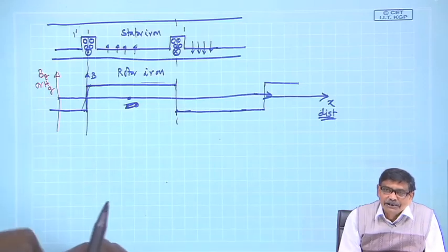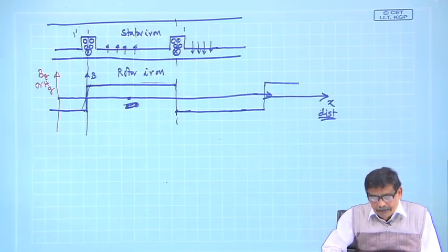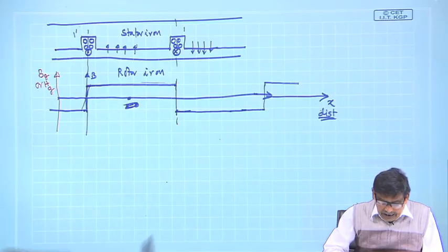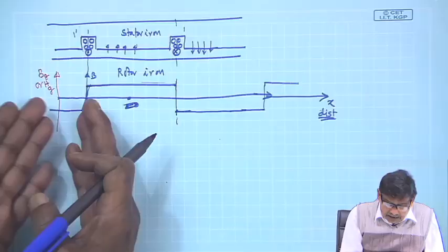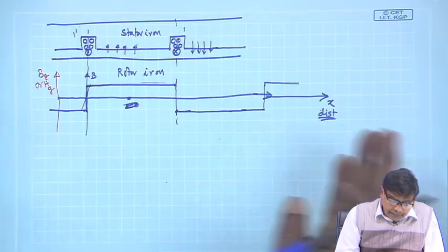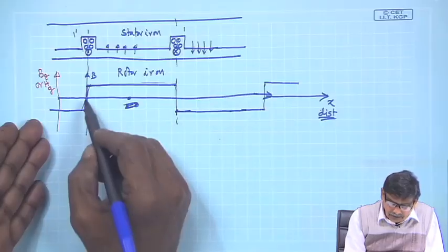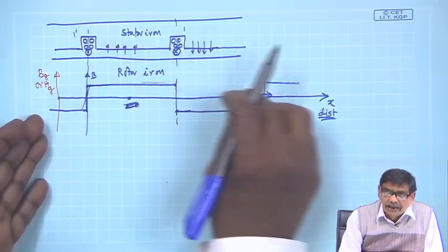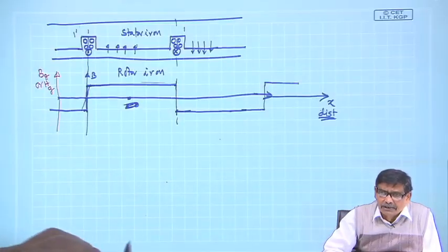If the B distribution is sinusoidal, your induced voltage too will be sinusoidal. But it is not going to be, as we are seeing with a single coil like this. At best you can say it has a strong fundamental sinusoid with a lot of odd harmonics with reduced amplitude. Perhaps you can neglect those and consider only the fundamental.